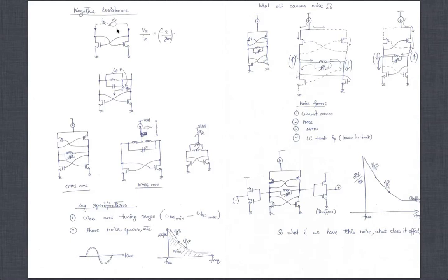One of the ways to simply do it would be, you can take this Vx, and I didn't draw it, I should have, and break it into two voltage sources. Here have a voltage source called Vx by 2 and another one called minus Vx by 2. So you can break this Vx into two of them and put a ground in the middle. If you put a ground in the middle, the total series voltage will still be Vx, but each will get either Vx by 2 or minus Vx by 2. If you solve that, you will easily come to this number here. I should have drawn it, but I hope you understand: take this Vx and break it into two series sources. The one on the left will be Vx by 2, the one on the right will be minus Vx by 2, and in the middle it will be a ground. You just put a ground there.